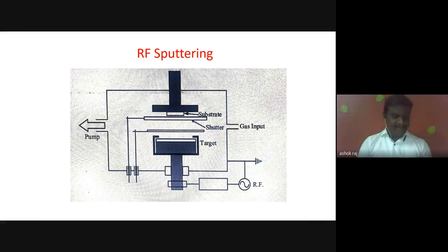In a radio frequency system, a high frequency generator is connected in between the electrodes. The high voltage RF sputtering source ionizes the sputtering gas and produces the plasma. A transverse magnetic field and an electric field are located under the target, which directs the argon atoms towards the sputtering target. Hence, multiple collisions take place. Finally, atoms of the target material are released into the plasma. Thus, atoms condense upon the surface, forming a new thin film.